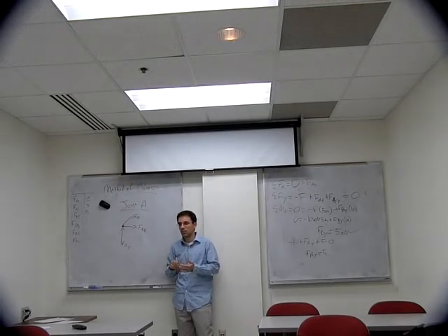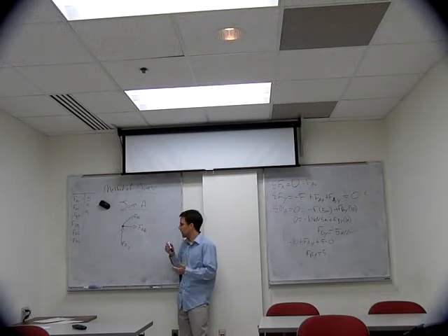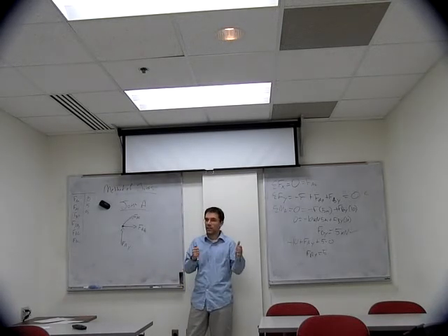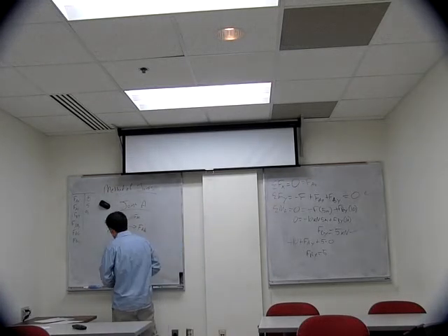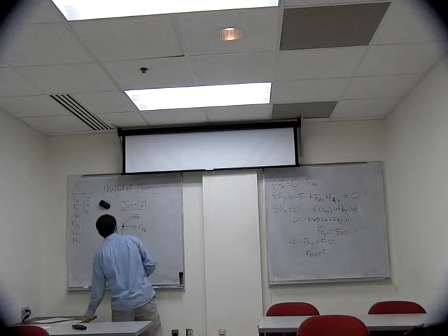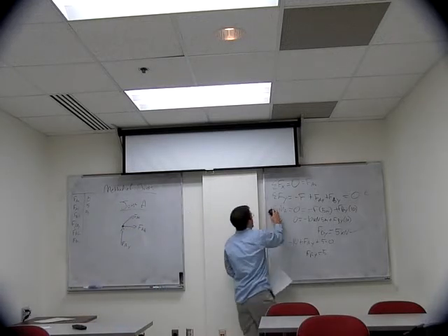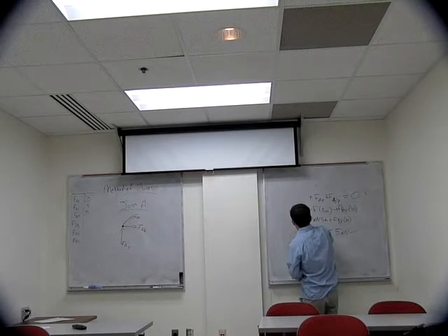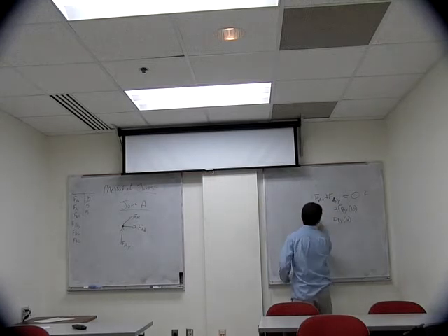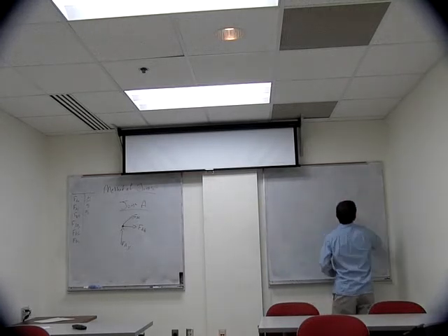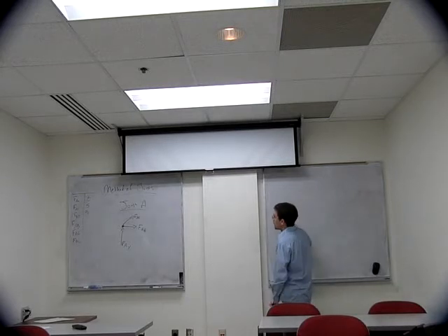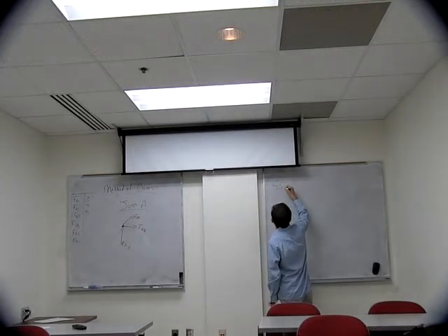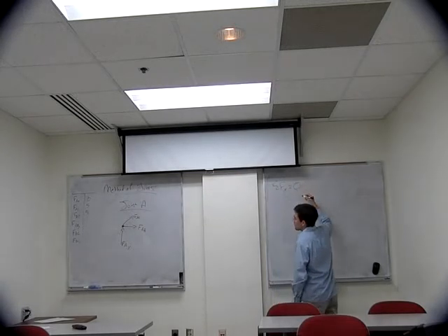And what you'll find is that it all works out in the math, and that if you end up with a negative tension, your beam will really be in compression. So just like before, what we're going to do is a summation of all the forces in X and a summation of all the forces in Y. So let's start with X, which we know has to be equal to 0.